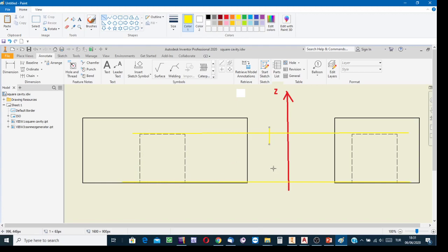And between the same transfer lines on the other side view, the left side view, we have another hidden rectangle. So if two views are sufficient and on both of the views we have a rectangle as the image of the feature, then this means it's a rectangular prism. But here be aware, this is the detailed drawing of a component.